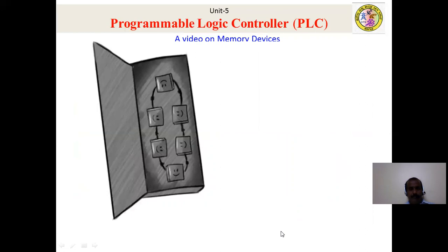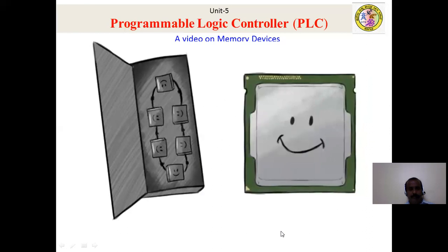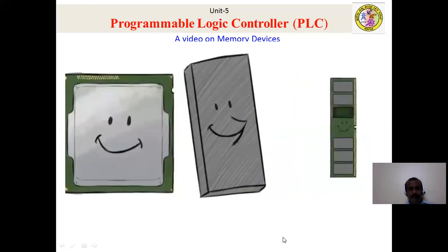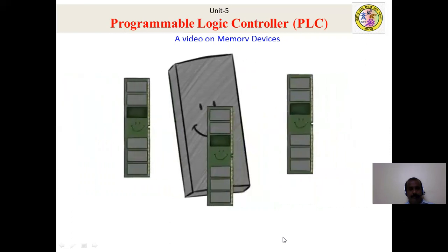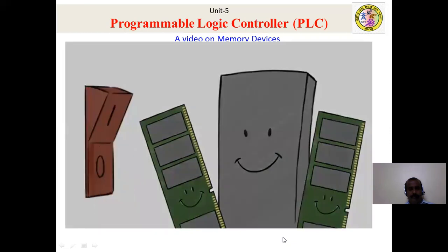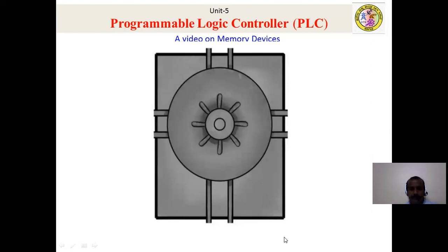That's usually made up of 6 interlocked transistors, which don't need refreshing. SRAM is the fastest memory in a computer system, but also the most expensive, and takes up 3 times more space than DRAM. But RAM and cache can only hold data as long as they're powered. For data to remain once the device is turned off, it must be transferred into a long-term storage device, which comes in 3 major types.